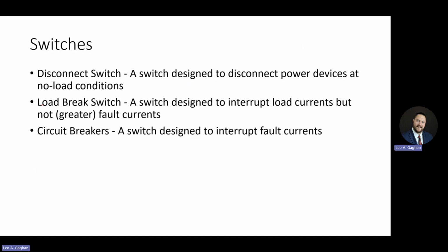So switches. A disconnect switch is a switch designed to disconnect power devices at no load conditions. It's not rated to break load. So in that situation, the circuit would need to be dead completely before we open up that switch. No voltage on either side.